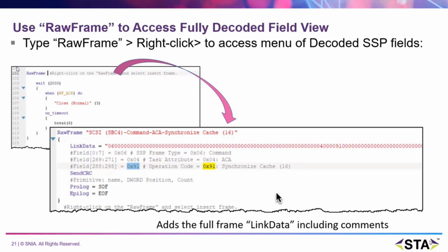In this example, we're demonstrating how the combination of an analyzer and its integrated exerciser capabilities can be leveraged for capture and replay testing. By replaying specific link conditions either exactly as captured or with targeted modifications, engineers can simulate a wide range of traffic scenarios.